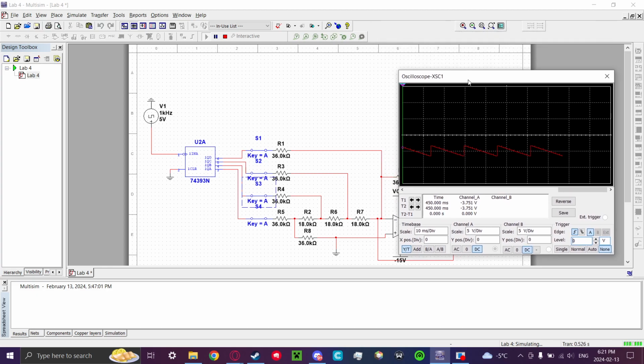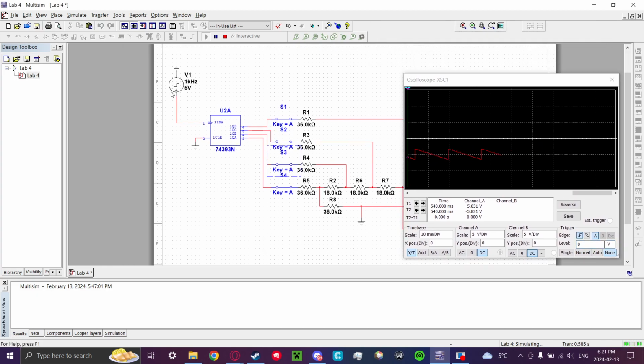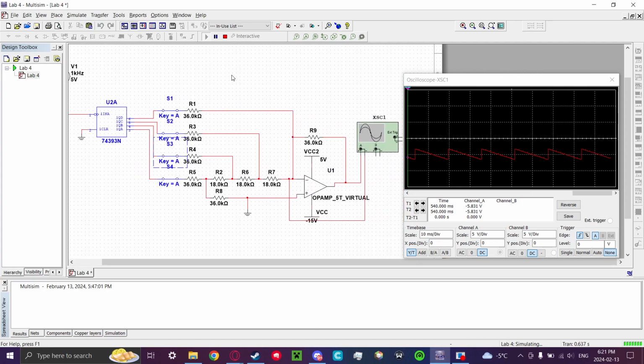So that's how this circuit works. It uses the square waveform through the binary counter to output a signal in one of the 4 outputs that goes to the operational amplifier and all these resistors. And messing with these will change in weird ways what numbers can be shown, depending on which outputs will be input into the operational amplifier and thus the oscilloscope.